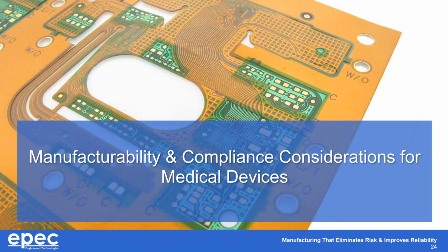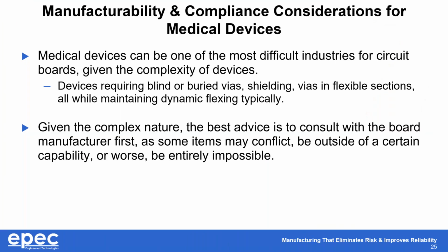And so for manufacturability and compliance considerations, the unfortunate nature is that medical devices are also usually extremely high tech, which is only unfortunate because then they start requiring things such as blind or buried vias, shielding, vias in flexible sections, and trying to maintain a dynamic bend radius, which ends up being juggling plates and trying to figure out how many you can juggle without dropping any.